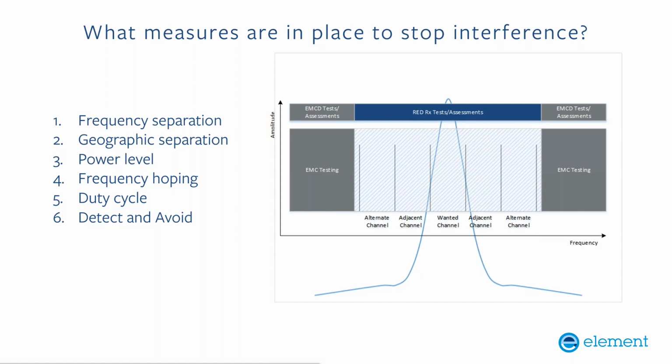And in order to resolve that and play nicely together, the way that we reduce the probability of interference is, first of all, making sure that we have different frequencies for different applications. So fundamentally, it's not ideal to have ISM and communication on the same frequency. We don't have the separation at that point. We could physically separate things so they have greater distance between them.